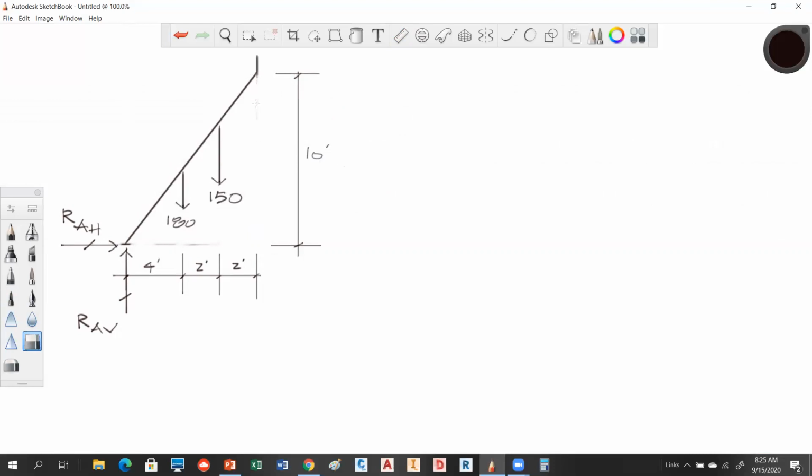Yeah, but a roller could go up, down, or left, right, but you told me specifically that it's going to the right. Because the wall is vertical. Right, so the force has to be what? Horizontal. Well, it has to be normal. It has to be normal, correct. So normal is the same thing as horizontal because it's 90 degrees to the surface over which it's rolling.